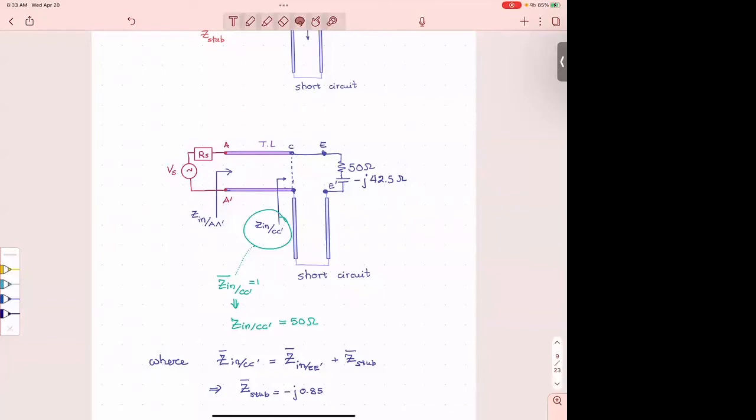So this one is asking me, can I go on this transmission line and put anywhere a stub like this? It could be short or it could be open at the end. All right, I can choose. But can I use one like that to then, at this point, make that 50 ohms? And if I use it, where am I going to place it? Am I going to place it next to the antenna? Am I going to place it somewhere else? So these are the questions, but visually, it looks something like that.